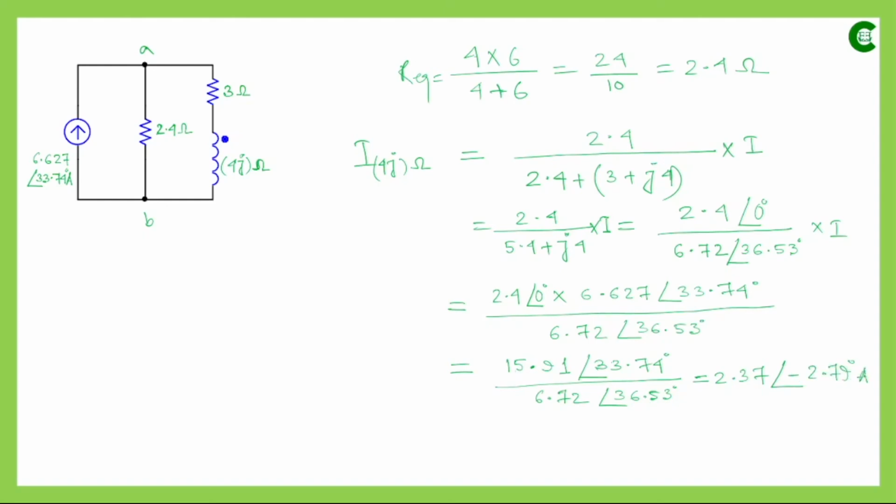And since this is the current value, this will be ampere. That means through this inductor, the current which is flowing, that value is this current value, and since this is an AC circuit and we applied an AC voltage source, the current which is flowing through this inductor also has an AC value. So it has a magnitude along with the phase angle. So this is the end of this class. Thank you.